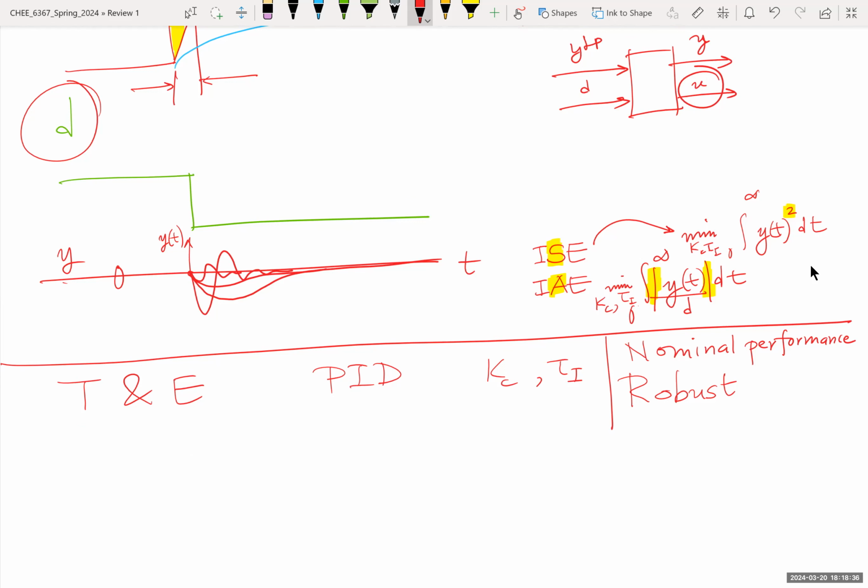The Ziegler-Nichols method is great, not so much because it gives you a super duper controller nominally, but because it gives you a robust controller. It handles the robustness case. Ziegler and Nichols knew that your model is going to be off pretty soon, if not from time zero. Same thing for IMC. IMC says, yeah, I can design a perfect controller. I can make the response perfect and all that. The real system is going to have some dead time that it didn't account for. It's going to have different gain, different time constant. Before I know it, if I overdo it with my controller aggressiveness, the closed loop is going to be so bad that it may even become unstable.